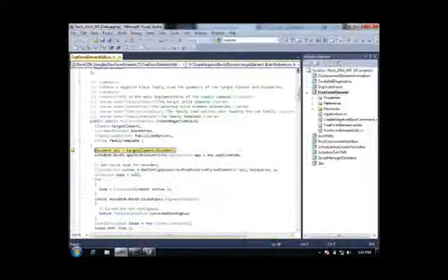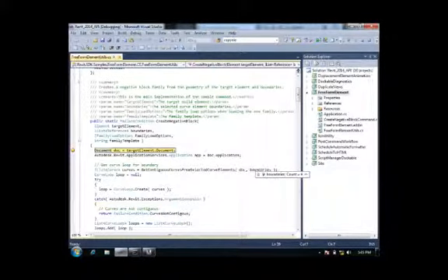and say finish. I've set a breakpoint in the helper method create negative block so you can see what is going on. The first method that we go to is the get contiguous curves from selected curve elements, which picks the boundaries and puts them together in the appropriate order to define a curve loop from them. I'll step over that.